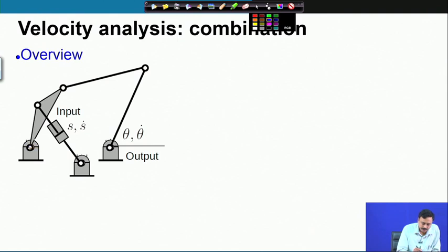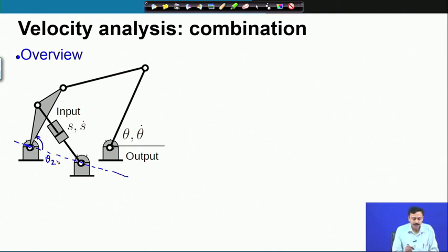Here the ground hinge of the 3R 1p chain is this, the ground link. So, this is the line of frame, this was our theta 2 for the 3R 1p chain. Now, given the input in terms of S dot, I can find out theta 2 dot.